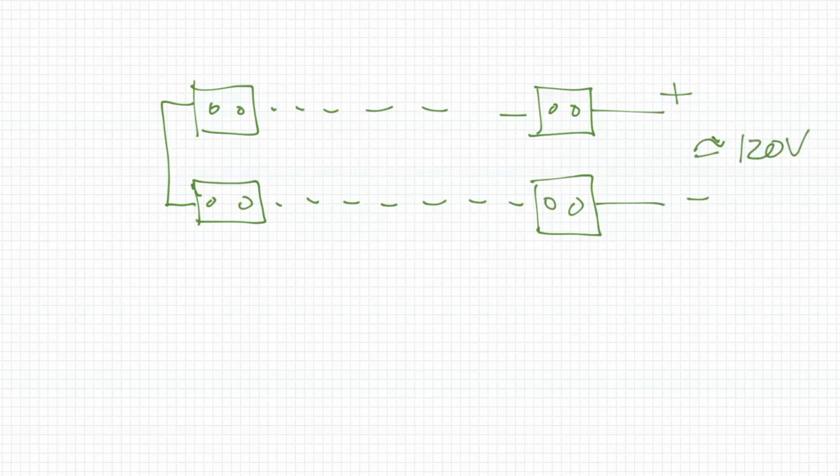Now the requirement is that LV battery systems, and that really now is over 60 volts, licensed electrical work, you need to bring it up to the same requirements as an NZS 3000 LV system, so double insulated cables, etc. This can't be accessible to the system operator, so it needs to be enclosed. But that question is about midpoint overcurrent protection and isolation.